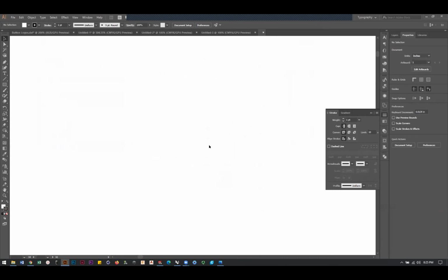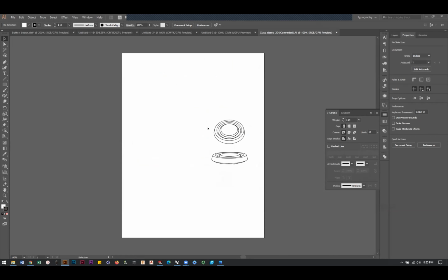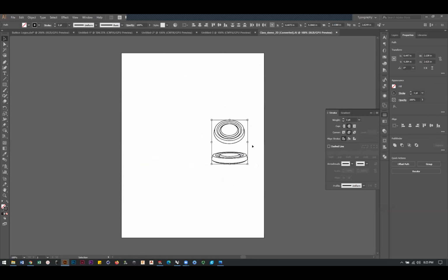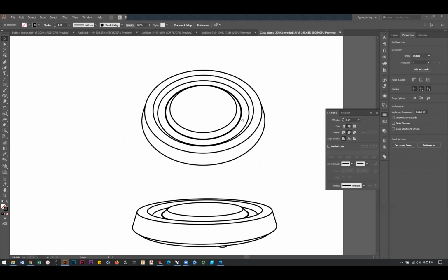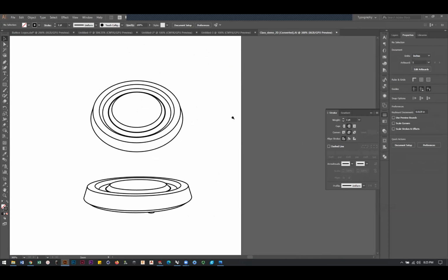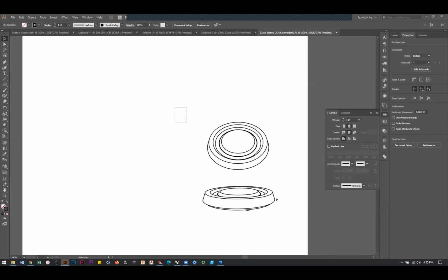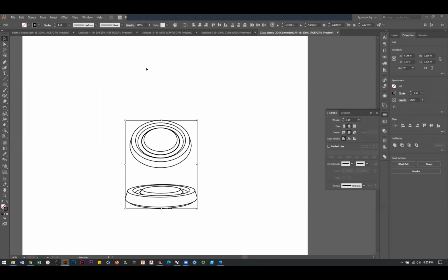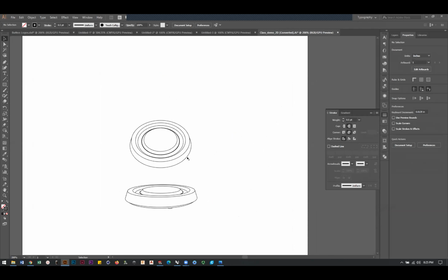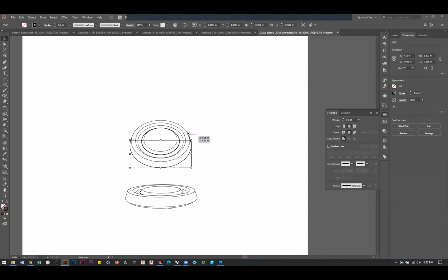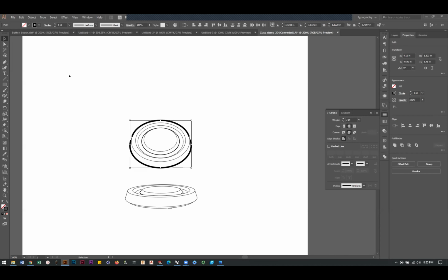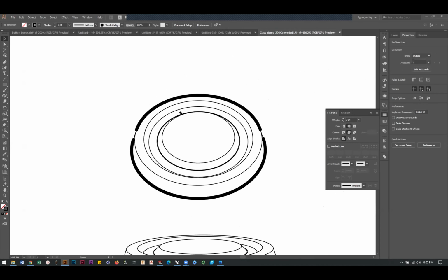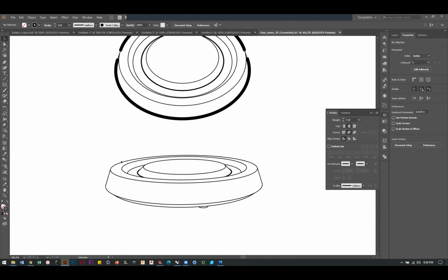Here's our 2D AI file, and here's our line work. So this is legit AI line work now, totally editable. Line weights can get changed to whatever you want it to be. Let's take a look at some of our line weights, maybe drop them all down to about 0.5. And you can grab the exterior ones, bump those up a little bit, fill in the blanks as needed to fill in the holes.